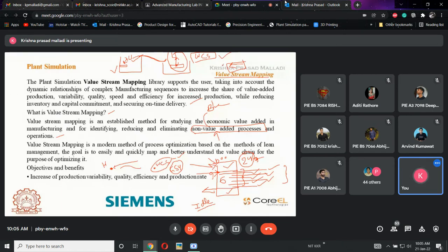At the same time, there is a part that is coming. We have programmed it in such a manner that the part is supposed to be fixed at the G54 which we have given. If I change the G54, there are a lot of things, G54 1, G54 2, G54 3, like different G54s, different work coordinate systems we can create. So if there is a slight delay in that, what will happen? The complete program will collapse.